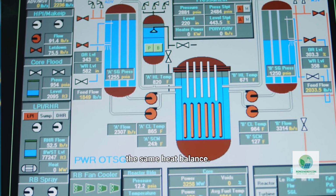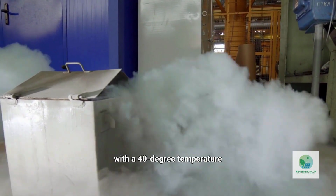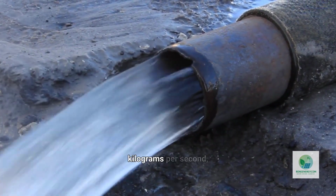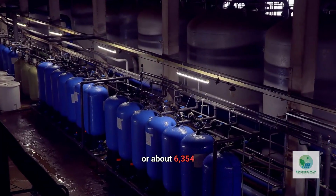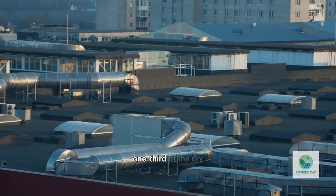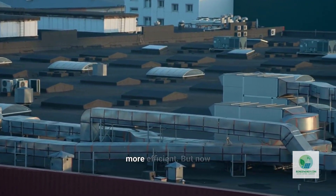Apply the same heat balance. To remove 17.7 megawatts with a 40-degree temperature rise, the required mass flow rate drops to 105.9 kilograms per second, or about 6,854 liters per minute. That is less than 1/3 of the dry cooling flow rate. Thermally, wet cooling is far more efficient.